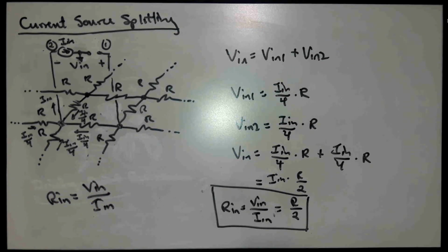I tend to use voltage source splitting when one side of the port is connected to ground, and I need to look at the voltage transfer characteristic, or even the resistance seen looking into the port, or the driving point resistance of that port. In that case, I'm probing it using the driving point conductance and then taking the reciprocal. As I mentioned, that is something we can do as a matter of convenience if we need to.